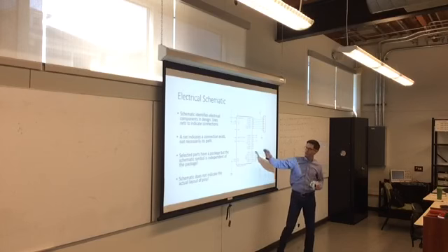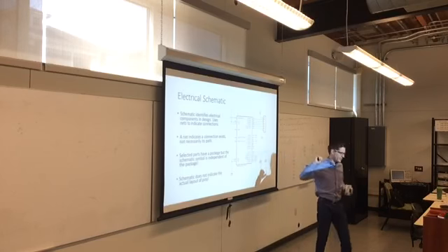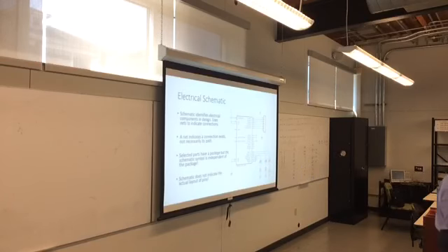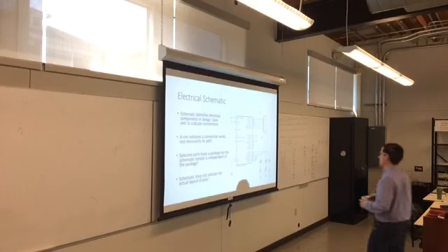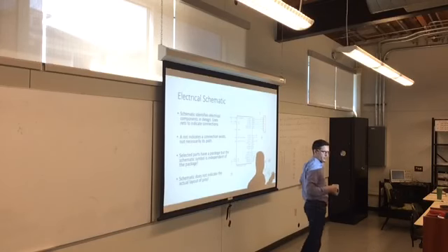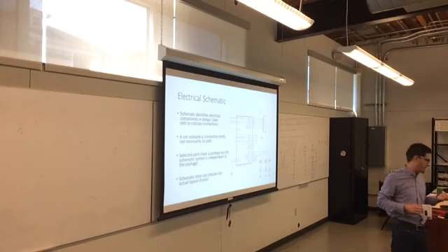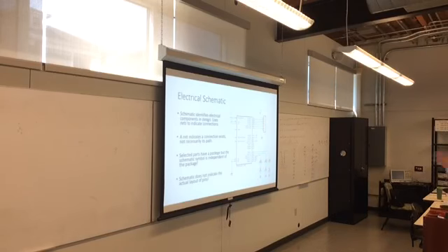At the same time, this symbol does not tell you how big that processor is. If you can read on the diagram, it says that it's a DIP processor, which means it's a dual inline package, which means it's your regular, if you remember the little ICs from EC220, just snap into the breadboard, that's a DIP package. So this is an old Arduino with a big DIP package. You can also get it in various surface mount packages, which makes it the size of like a fingernail. This schematic visually does not tell you what pin package it is. You'll have to dig into the particular part that's selected, and you'll have to read what pin package it is.